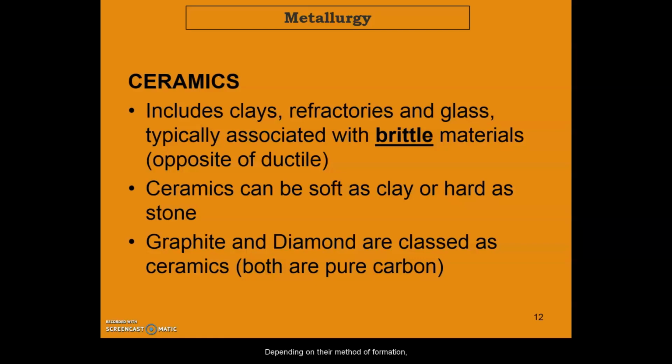Depending on their method of formation, ceramics can be dense or lightweight. Typically, they will demonstrate excellent strength and hardness properties. However, they are often brittle in nature. Ceramics can also serve as electrically conductive materials or insulators. Some ceramics, like superconductors, also display magnetic properties. They are also more resistant to high temperatures and harsh environments than metals or polymers. Due to ceramic materials' wide range of properties, they are used for a multitude of applications.